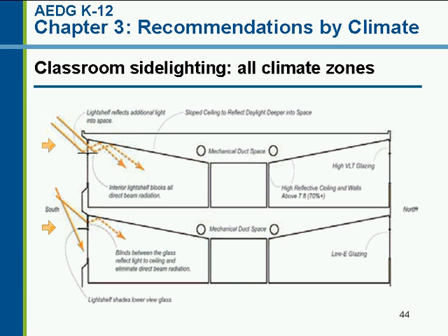And on the first floor, you see the other part of that graphic. To the extent that you've got that overhang, it's going to block the sun from coming through the lower portion of the window there, so there's less glare on any students that are at desks near the window.